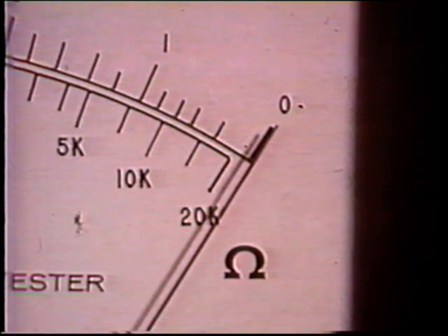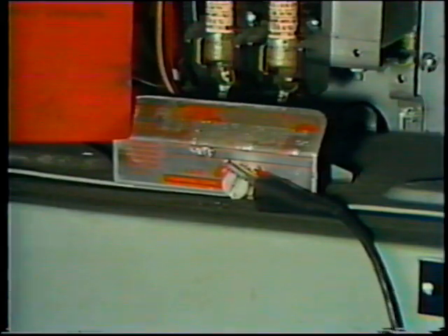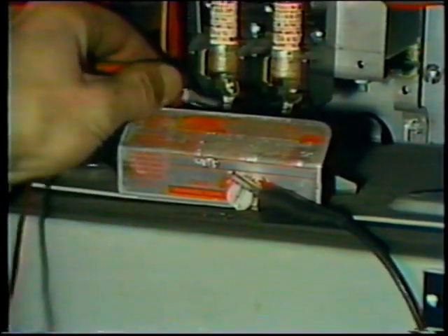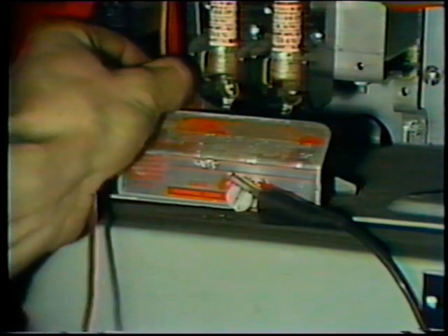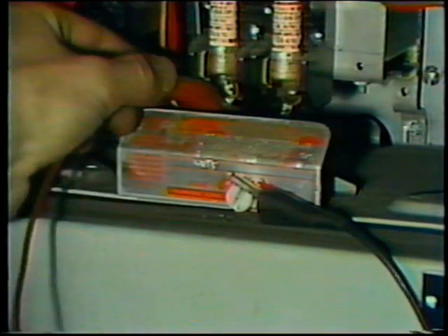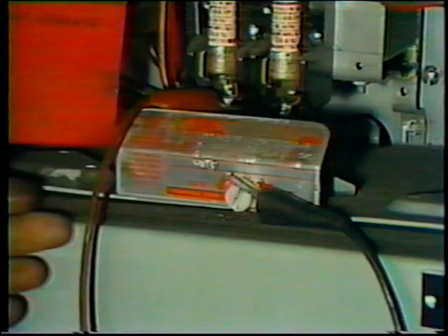After testing the megohm meter, the electrician is ready to measure the resistance to ground on the output of both fuses. He connects one probe to the output of one of the fuses. This will give him a reading from the fuse to one side of the start switch. He takes his reading. The reading shows high resistance or infinity and indicates that a ground does not exist in that part of the circuit.